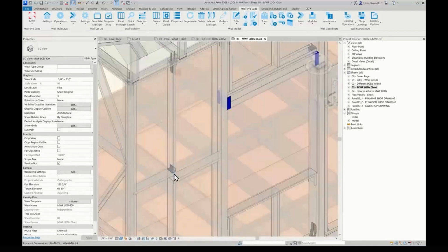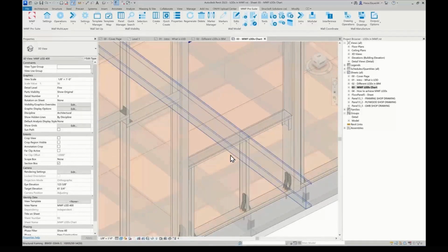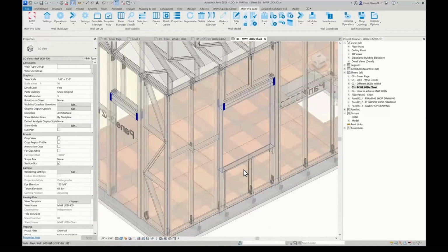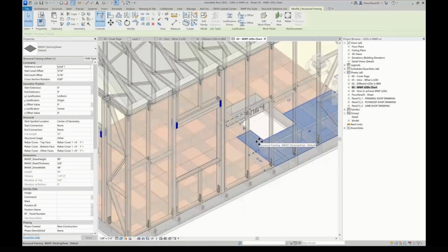Connection content is very important. So connection content is developed in the wall elements. This includes, but is not limited to, fasteners, clips, and other related hardware. Cladding and sheathing are also definitely shown in this stage. I've shown them for the floors. So if I tab here, you'll notice I did add them for the floors.